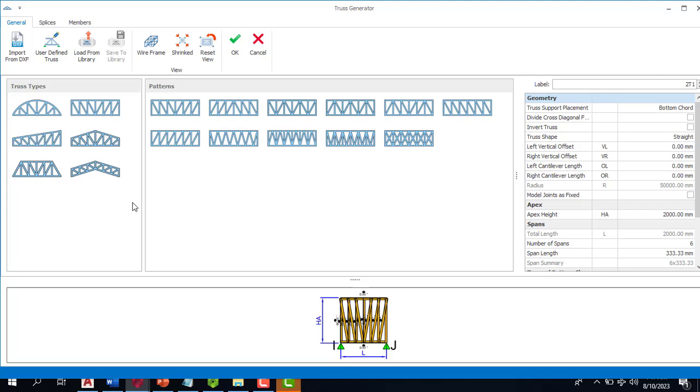But even at that, there are some steel patterns that may be a bit more complex than this, that are not going to be very easy for you to achieve by modeling directly from ProtaSteel. So you can simply import from DXF, which I'm going to be showing you in the next episode. So I'm going to be showing you how to import a steel truss.